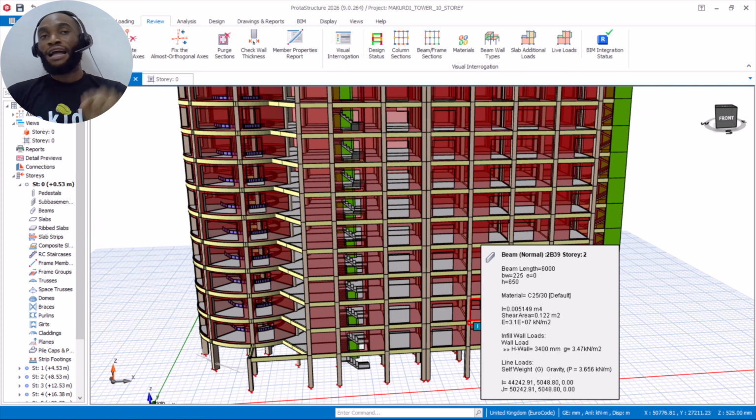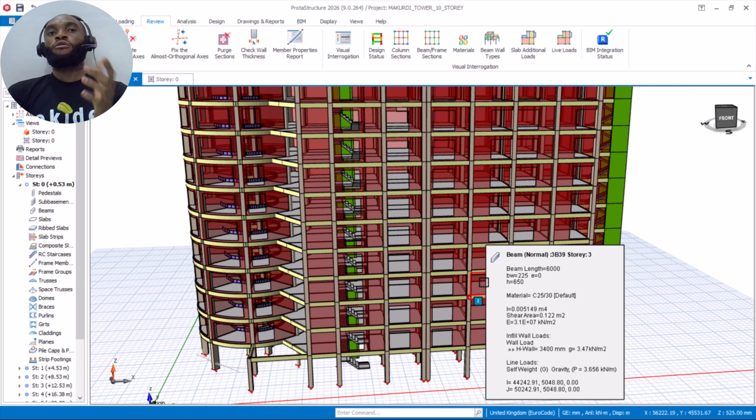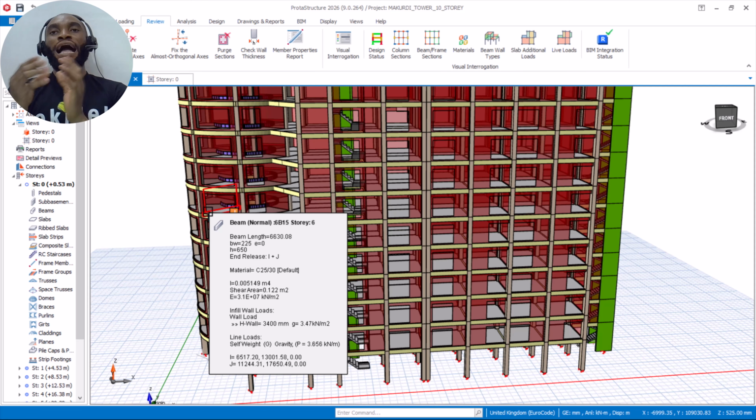There will be cracks inside the ground and you will not know. Before you know it, it will cause a collapse, because there is already a crack on each of the piles that they've already piled. Those cracks will happen when your pile spacing is less than the required standard, which is 2.5 times the pile diameter or 3 times the pile diameter.